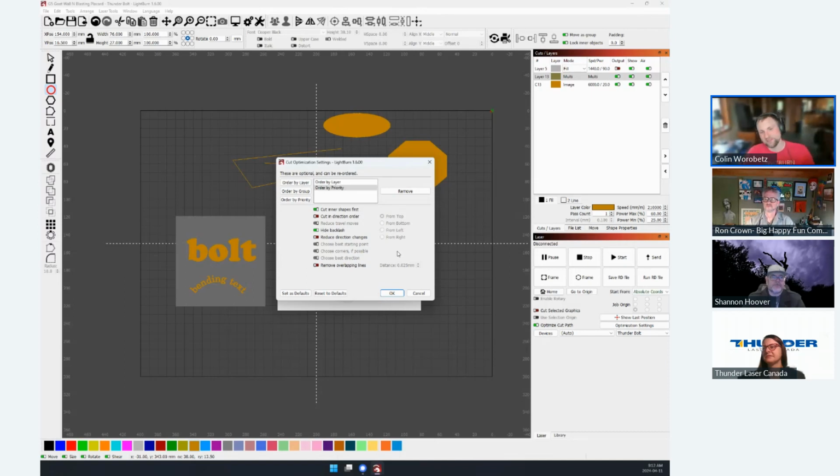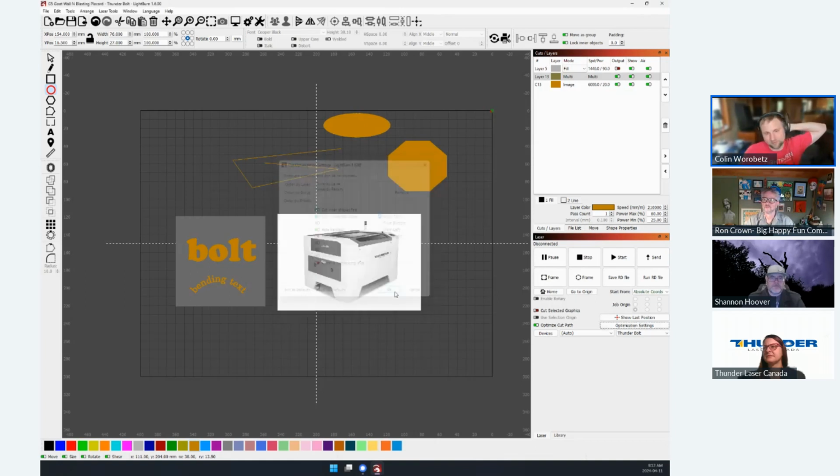It starts from the same side of every cut. If you have a loose machine or an older machine, that can help. Or what you should really do is maintain your machine. All these are really good ways to optimize how your cuts work for your specific jobs. If you have small lettering or you're doing big parts, where things start is important, and there are tools within LightBurn to make that job easier.